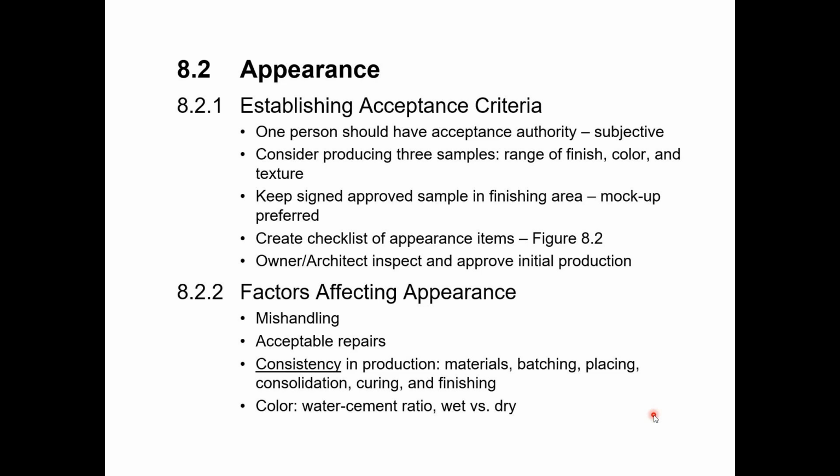So mishandling is something that's very common that we'll see in storage yards where something got chipped or spalled because it wasn't handled properly. There are acceptable repairs. This also needs to be something that is presented to and approved by the owner or architect. That, okay, if something has to be patched, this is what it will look like, and we'll blend it in as best we can, but it may still be a bit visible to the discerning eye. That needs to be something that's shown to them. Otherwise, any panel that ever had to be patched might have to be fully rejected if the architect doesn't approve that process.